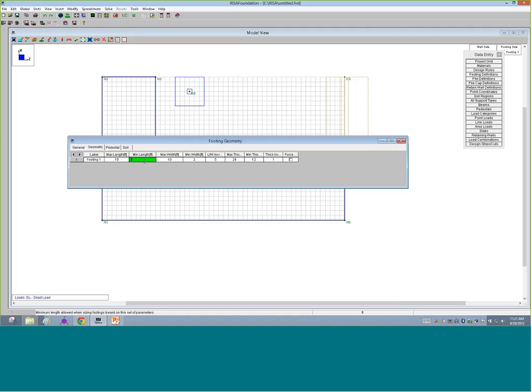If you decide, hey, I already know what size I want, I specifically want a 4x4 footing, you can set the program to be 4x4, and that's just as easy as telling the program 4x4. Just a title maybe that we'll say set 4x4, so I give it a name that maybe means that. And I can tell the program here, give a maximum length of 4 and a minimum length of 4 and a max width of 4 and a minimum width of 4. And that way, now I'm not really doing a design on that. I'm not sizing it up or down. I'm just checking what you already have told me I'm going to use there. And so that's all set up.